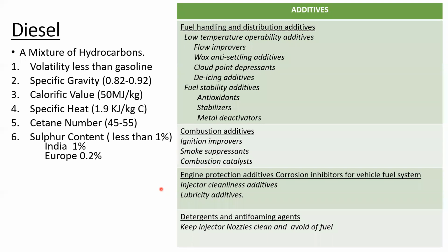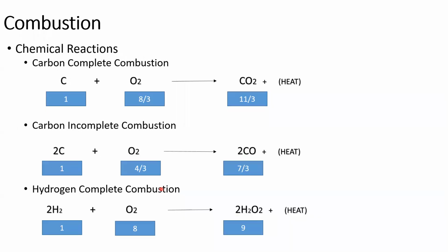Once the foam is created, the fuel cannot be pumped. If it changes into a foam, it's very much like a gas, so it cannot be pumped, and the vehicle cannot operate. The same thing happens in petrol: if you have higher temperature, it creates something called a vapor lock. The situation is somewhat like that. So to reduce the foaming properties of diesel fuel, detergent and anti-foaming agents have to be included.